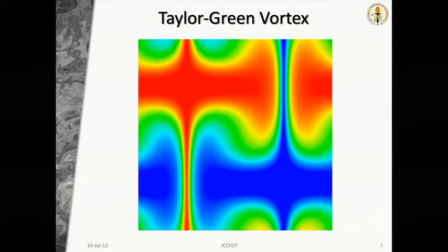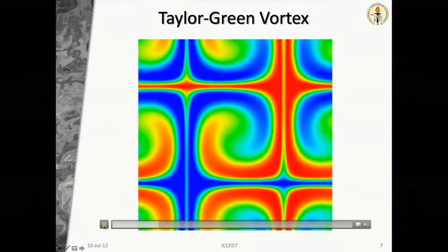Numerically, if you don't implement physical diffusion, what should happen? You're going to have a thin gradient between the layers. Yeah, the scalar will keep getting stretched into thinner and thinner filaments, and it should not diffuse out. Okay? The only diffusion you will see, if any, will be because your numerical scheme has some errors. So let's play this and see if we see any diffusion.